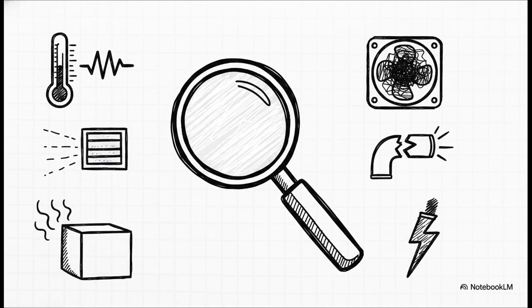Okay, so you step out onto the tarmac and start digging into the machinery. Treating this whole thing like a crime scene, you gather up your initial raw symptoms. First up, the cabin temperature is just completely unstable. Second, the physical airflow actually reaching that aft cabin is noticeably weak. And third, the air conditioning pack itself is running at an abnormally high temperature. You do a quick physical sweep and note 3 rough observations: a dirty cooling fan, a small leak in the ducting, and a history of an intermittent temperature sensor fault. So, those are our clues.